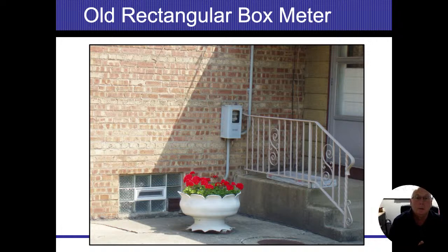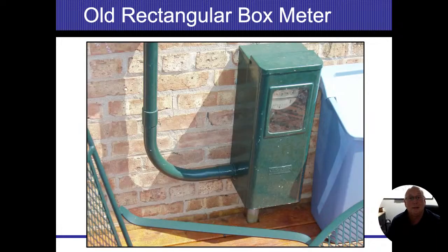But yeah, if you start seeing 100 amp services on these things, that means somebody changed the panel and the wires coming in there. I don't think it's necessarily the end of the world, but a problem is never a problem until it becomes a problem. And if these things are only rated for 60 amps and we're seeing 100 amp service coming in there, we should be calling these things out.